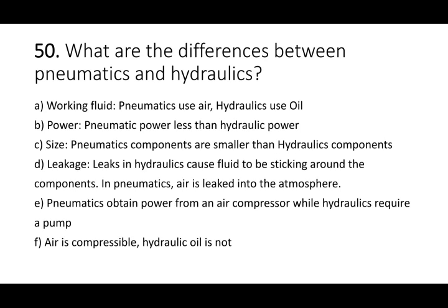Then leakage. Leaks in hydraulics cause fluid to stick around the components. As we are using oil, that oil may stick to the outer surface of the system. Whereas if the air leaks from the pneumatic system, it will go into the atmosphere. Then pneumatic obtains power from the air compressor, while hydraulic requires a pump. Then air is compressible, whereas hydraulic oil is not compressible. So those are the differences between the pneumatic and hydraulic system.